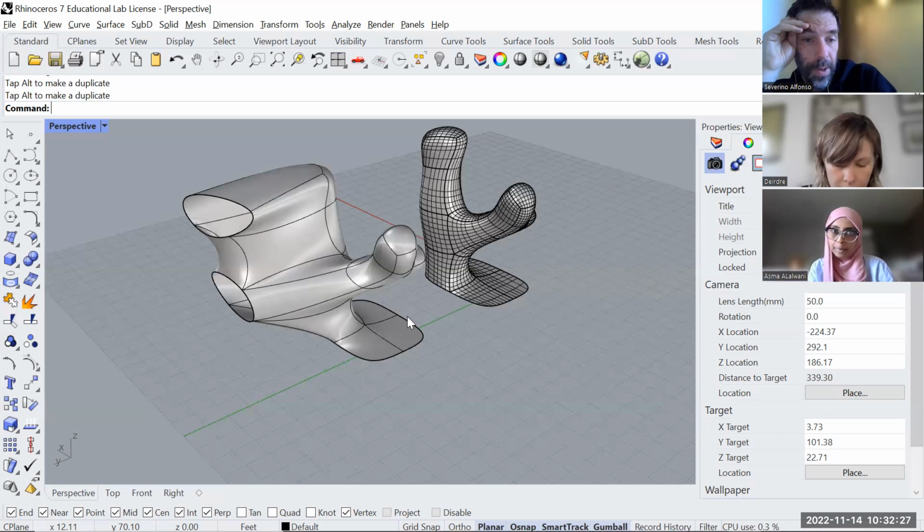And then you have it. You have it in Rhino, which means that you have it in Revit, theoretically. So you will be taking it to Revit. There are 2 or 3 different ways to do that, but probably one of the best is as an SAT or as a DWG. I can send you some links of how to do this. Or I don't know, you're rendering in Revit normally, no?